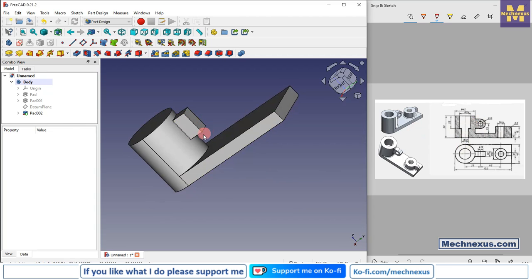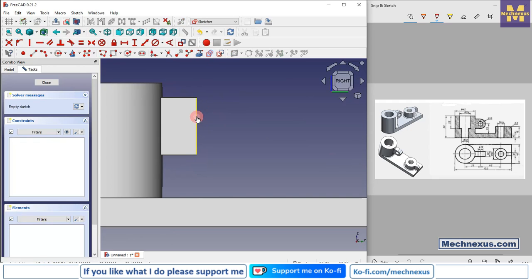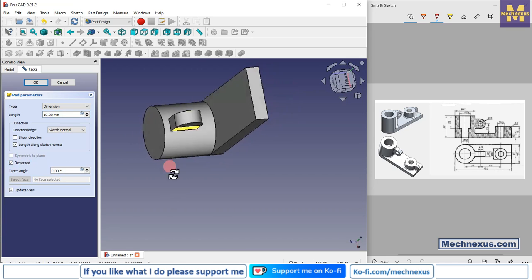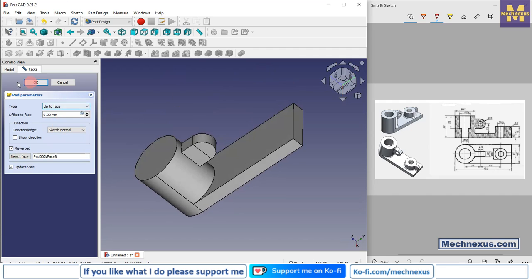So instead, we will add a material. We will select the face and click on the sketch, click on project geometry, because we have created our datum plane to this axis, so this means that this portion we have to add the material. We will select a 3-point arc, select this and this, and add a coincidence, select the line tool, close the profile, click on close, and here we will select the sketch, click on extrude, say reverse, and from the other side we will select a face and click on OK.